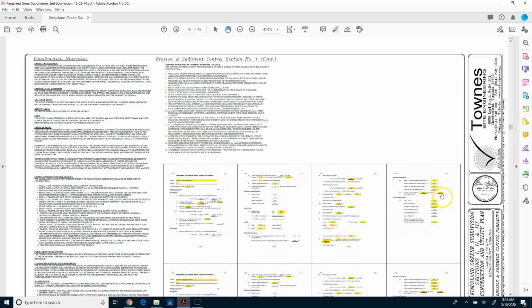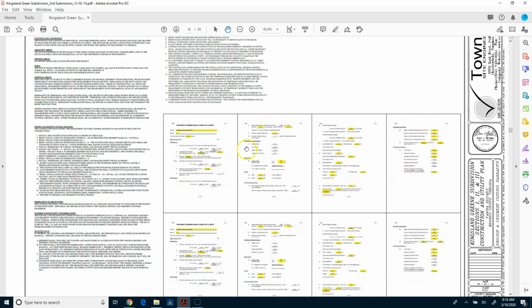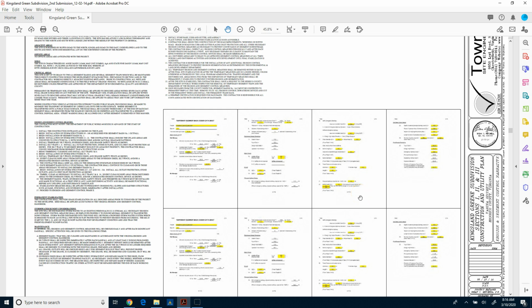The next sheet here is typically along the erosion control is the sediment and notes. So there's a whole narrative that explains how this material and how the sequencing should happen. And again, we won't go through and read all those details, but then even here is their computation. So it's showing how they computed and what for the basin, it's important to make sure they've got the right volume. So therefore, they would have that information shown here is how they calculated it.